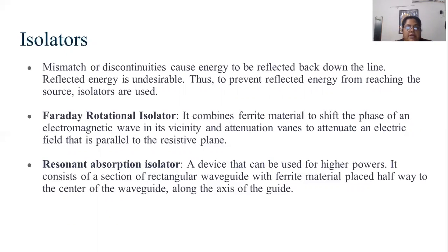Faraday rotation isolator. It combines ferrite material to shift the phase of an electromagnetic wave in its vicinity and attenuation vanes to attenuate an electric field that is parallel to the resistive plane.